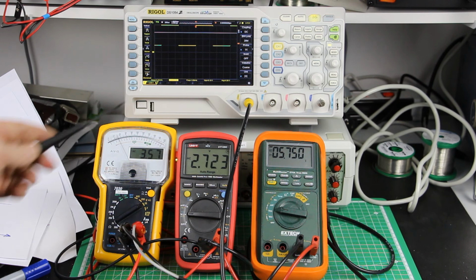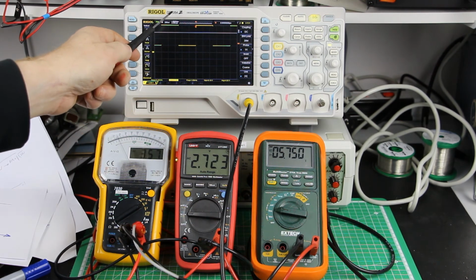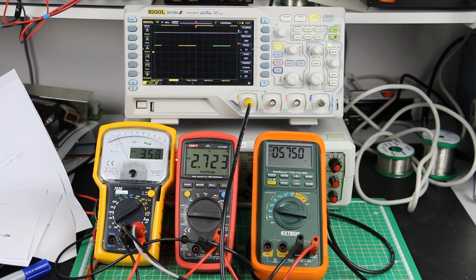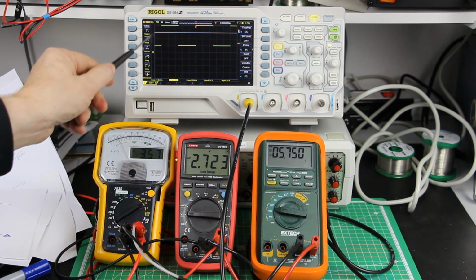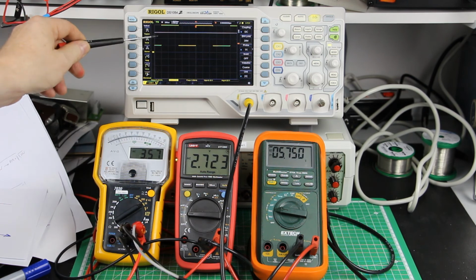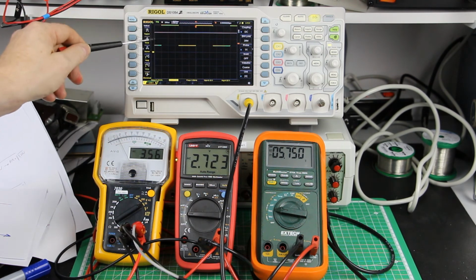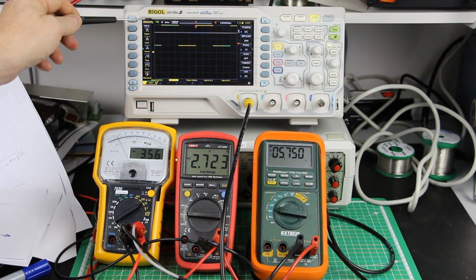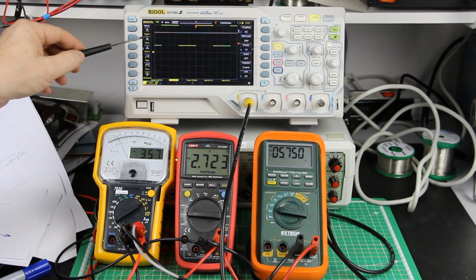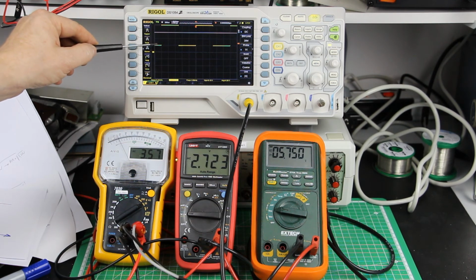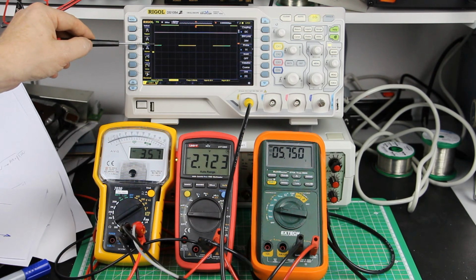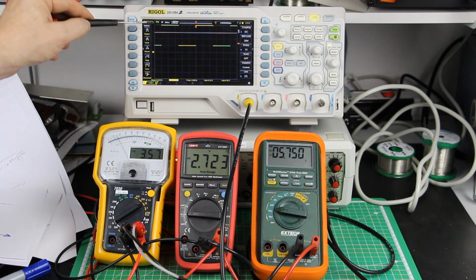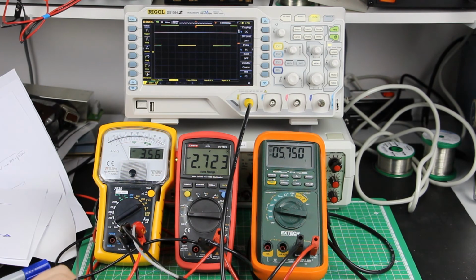So now we can see on our Rigol DS1054Z digital oscilloscope what the real waveform is. As I told you, it's a symmetrical rectangle signal, but with a DC offset of 2 volts and a total amplitude of 6 volts. To be honest, I cannot exactly set the offset 100% to 2 volts and 100% to 8 volts at the peak voltage, but anyway, that's